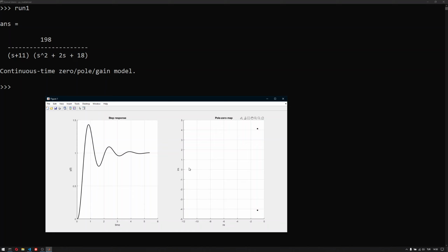And the assumption is that this pole will not affect the pole pair or the overall response that much, which we will verify and see in the next lesson, by the way. So bear with me. If you don't really get the idea here, we will examine it in the upcoming lesson. And we see that it takes almost 4 seconds to reach this point, which is around 1, and it will wiggle around this kind of value, but not that much, so we kind of are satisfied with 2%. So this is the point where the settling time is almost equal to 4.